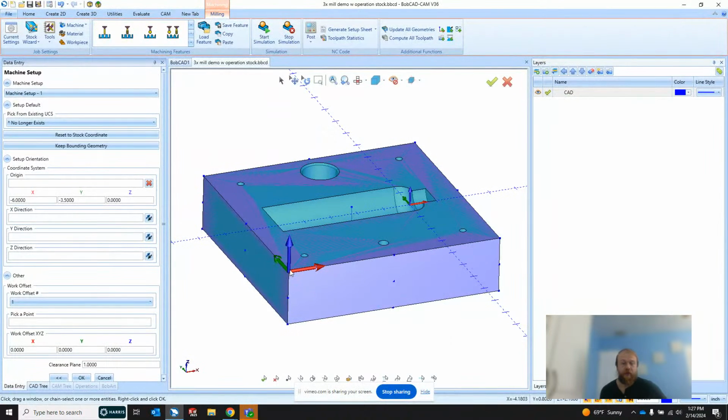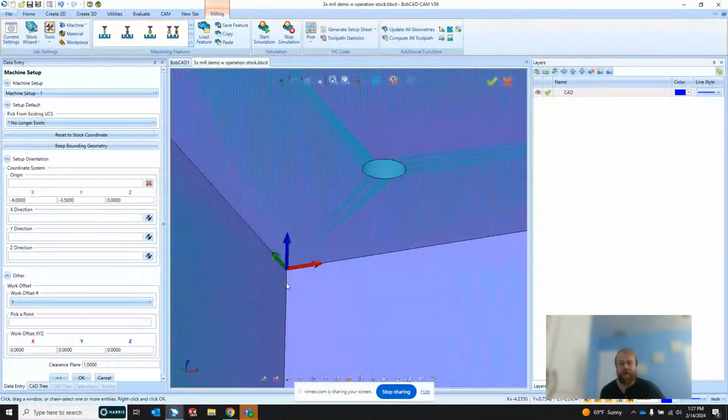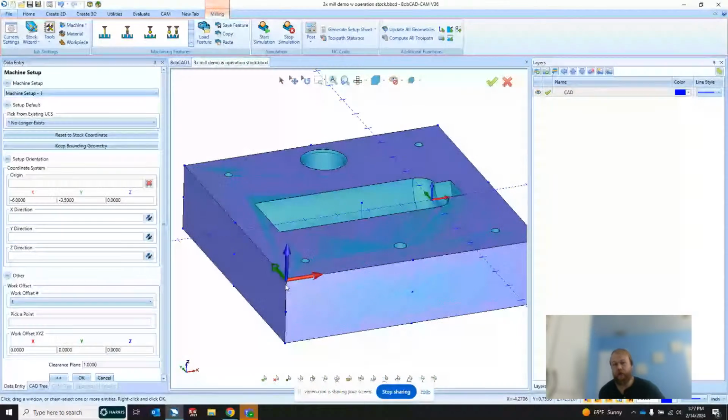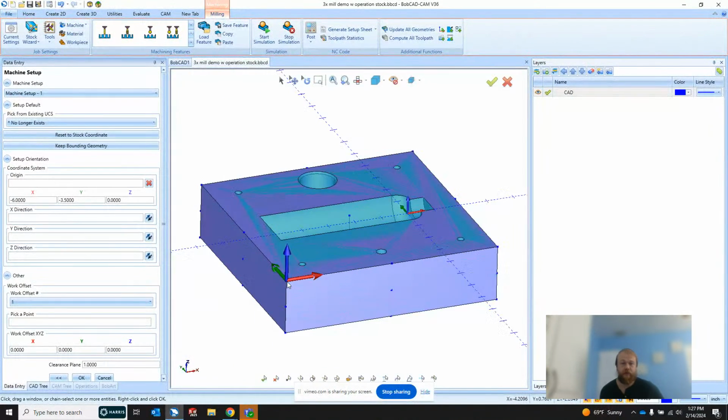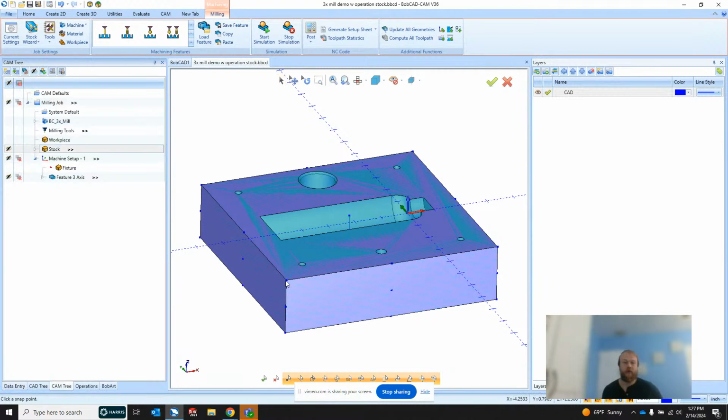We can touch off the tool down here at the bottom left corner, or if we're using a probing tool or an edge finder, for example, touching off at this location, I highlight the origin point and click on that point for our new G54 work offset location. And that is where we start our milling operations.